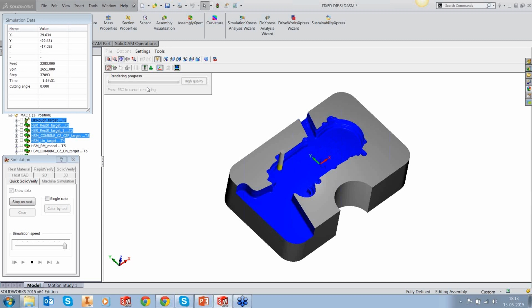So even in spite of doing so many roughings, you will see that we have introduced another rest machining toolpath to make sure that even in the corners, the tool doesn't encounter uneven material. So we've done a lot of toolpaths before we actually hit on the finishing.